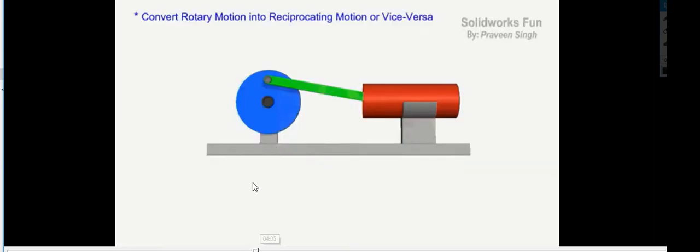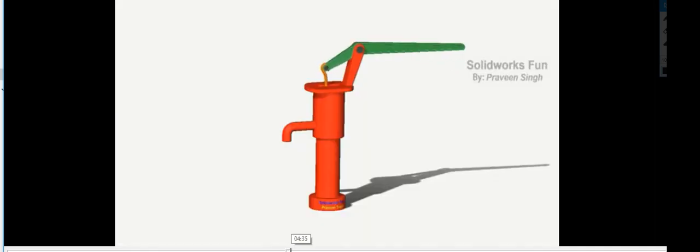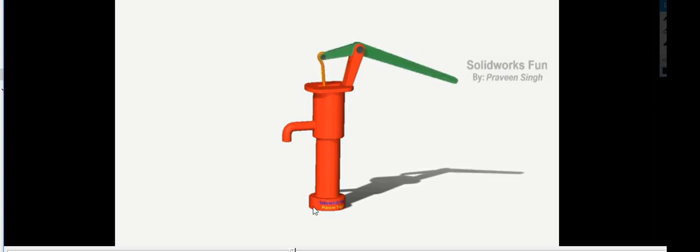First inversion was the reciprocating engine. The basic slider crank mechanism itself is the first inversion. Second inversion is the hand pump, which we learned just by this animation. We're not going to detail or draw any figures of the hand pump. Then the third inversion, which is important to us, is the oscillating cylinder engine. Still, we only need to learn the names of those.